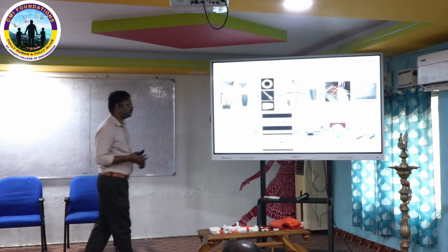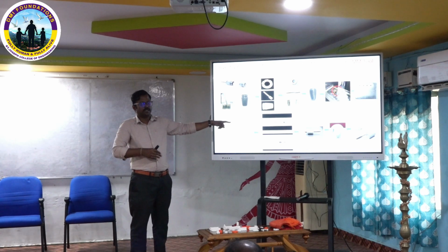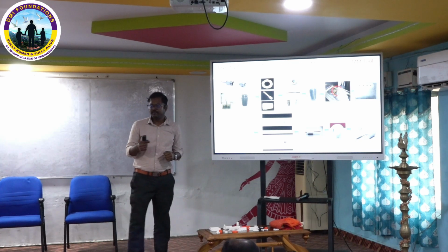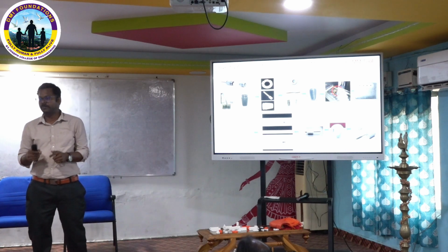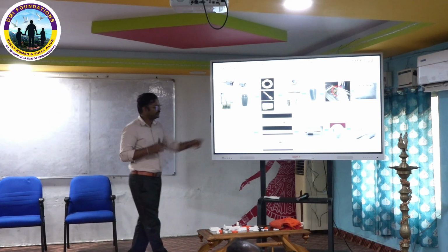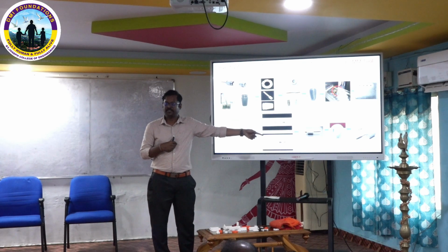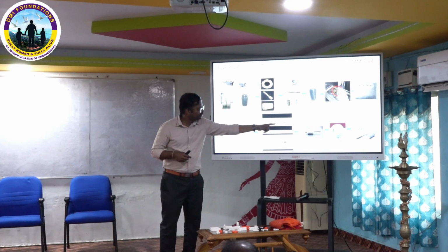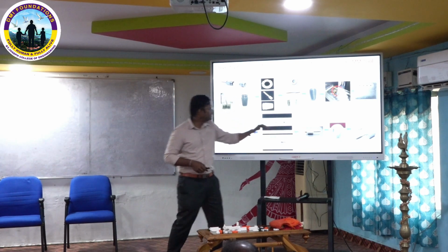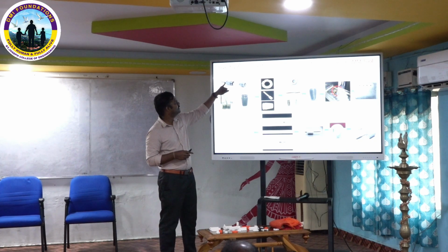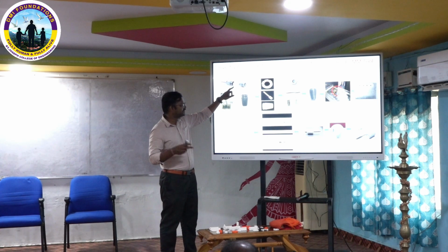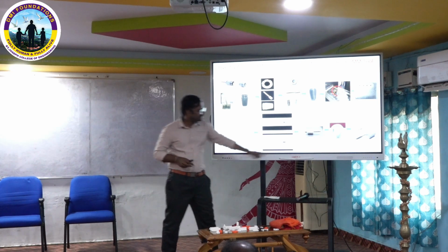Another objective of this work is to redesign this tool holder. Why? Because it has 3 components, which is not an issue by itself. But when tightened with the tool, if the tool diameter is 0.3 mm or 0.4 mm, it breaks or deforms. So I incorporated part consolidation theory here and changed the 3 components into 2 components. In that also I electroplated only one part. The names of these parts are shank, collet and holder. I merged the design of collet and shank as a single unit.